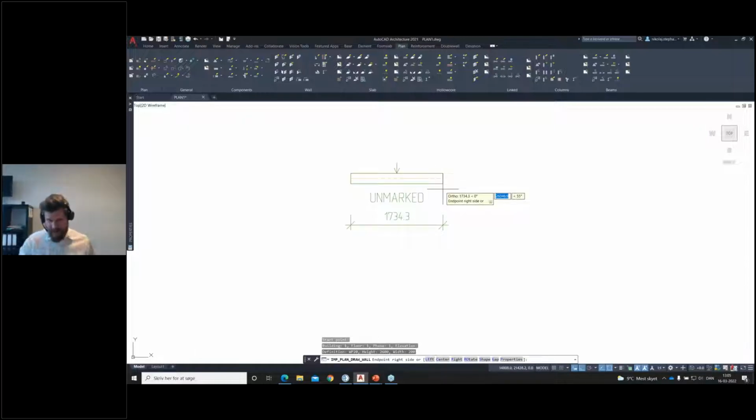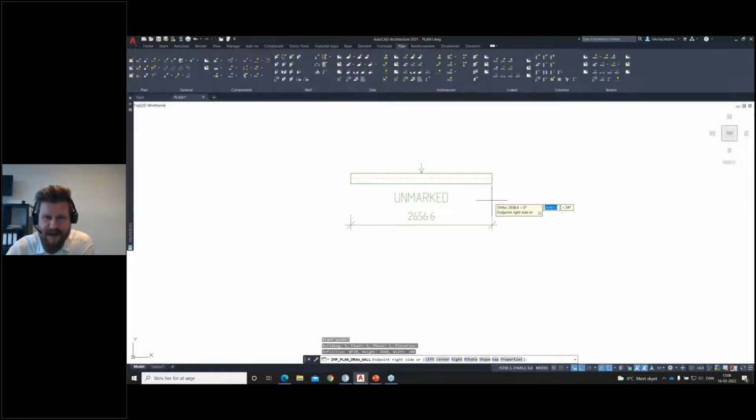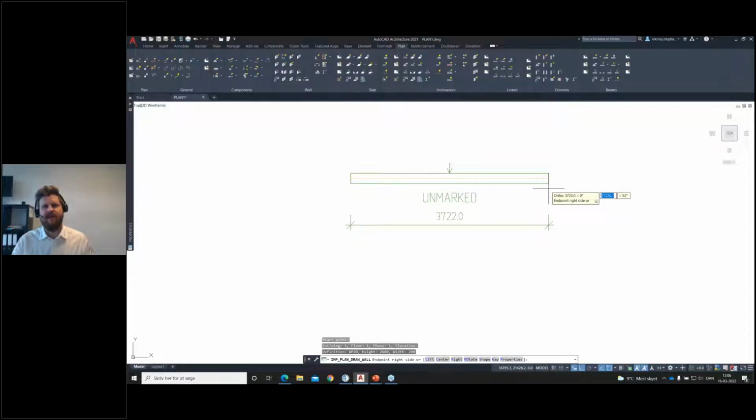For those of you familiar with Impact, you'll see straight away the difference here. We get an arrow and we get this measurement line down below as well. Again, it's a smaller thing, but then again not, because at this point where I only have a preview, the arrow symbolizes where the bracing side of the element is. In this element type, I have my number marking side on the other side of the bracing side, which is the up in mold side, of course. A little technical for those of you who don't know Impact. For those of you who do, I think it's completely fitting.